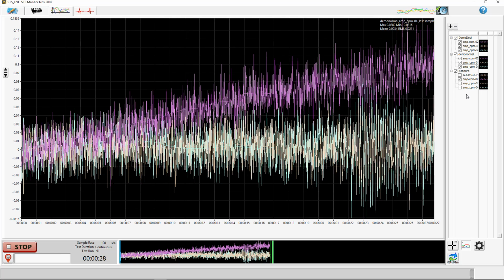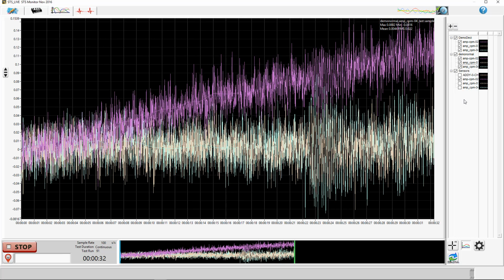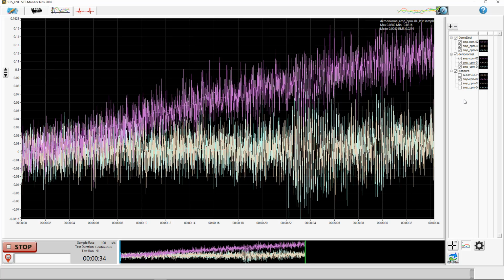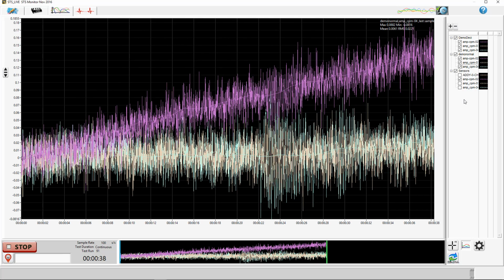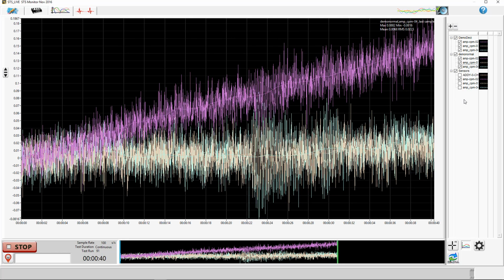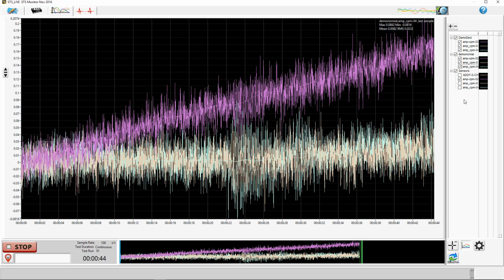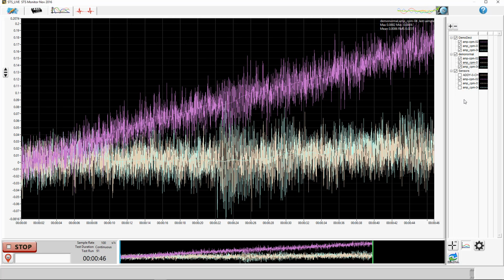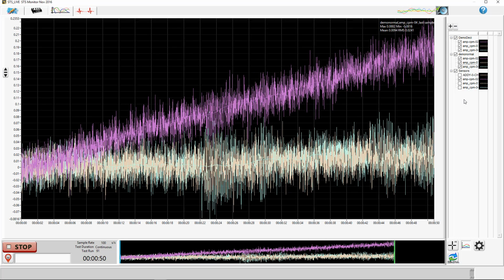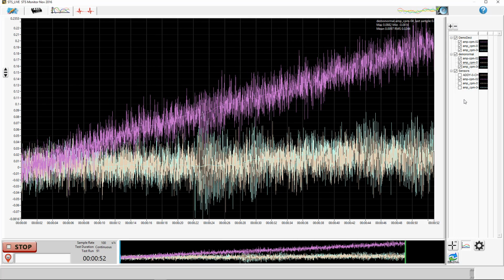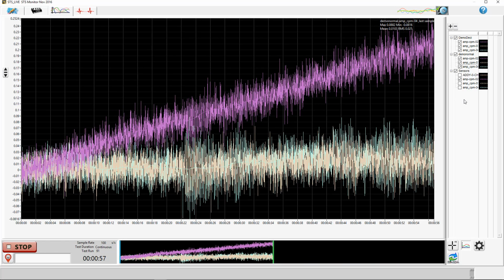Please remember that most of the time you will be talking to a remote site where the core runs, and all this information has to be transferred over a TCP/IP connection. If that is a modem, then the data rate of that modem is very low and you cannot maintain all these sensors. If you have a large sensor count, it would clog up the whole channel. So we do not automatically enable these sensors for data retrieval. You have to do it manually.